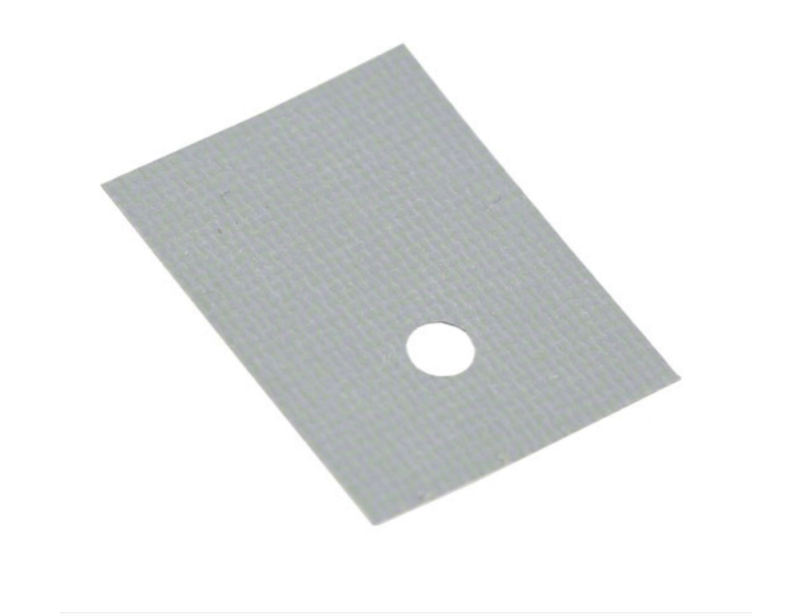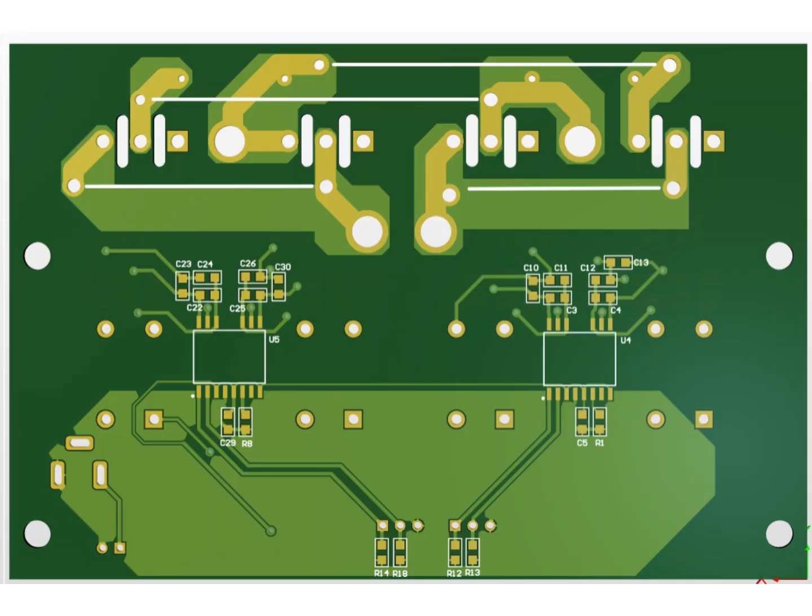This arrangement provides excellent thermal coupling, keeps all power devices on a common heat sink, and ensures mechanical stability of the assembly. At the same time, soldering the leads on the top side allows for strong electrical joints and easy inspection after assembly. From this PCB layout, the electrical isolation is clearly visible between the high-voltage power stage and the low-voltage control and gate drive circuitry.